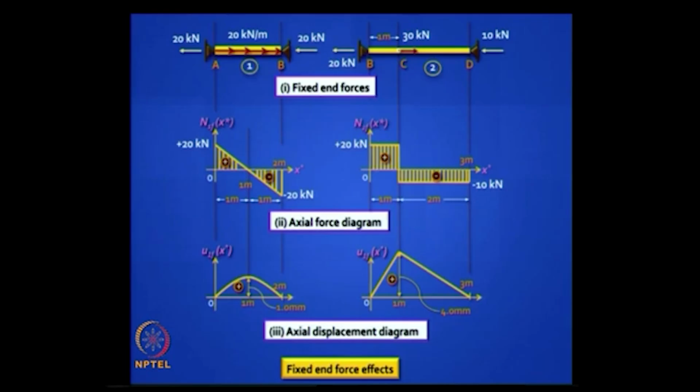Well, you can't handle it if you have only 1 degree of freedom per element. So forget about how to handle it in a mathematical framework, just put it all together manually and tell me what F1, F2 and F3 are going to be. What are the equivalent joint loads due to the intermediate loading? Can you tell me what F1F is?